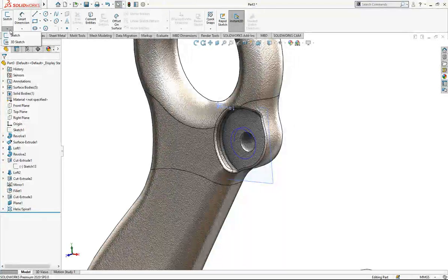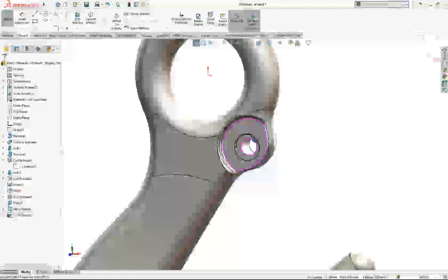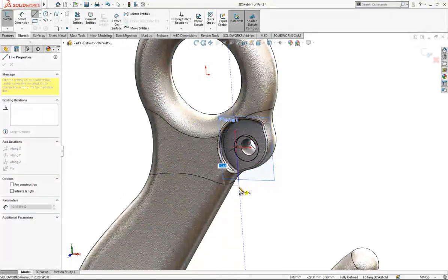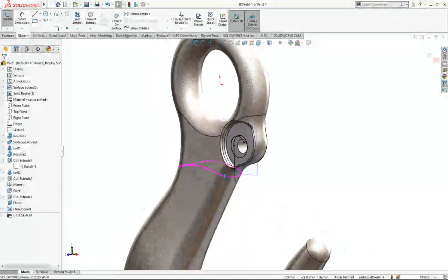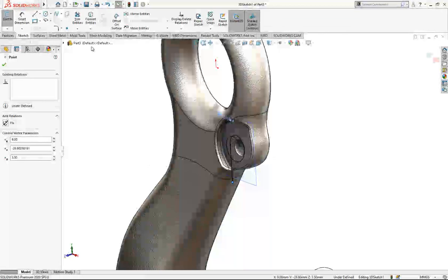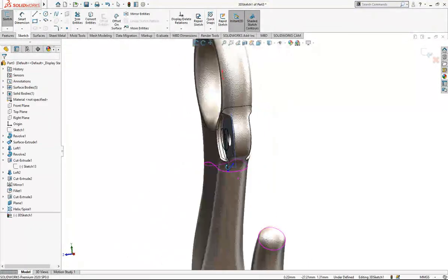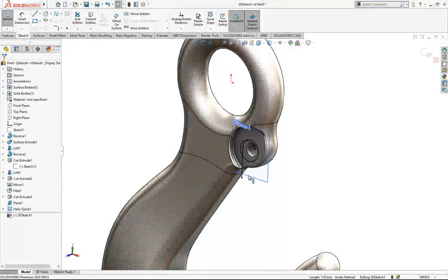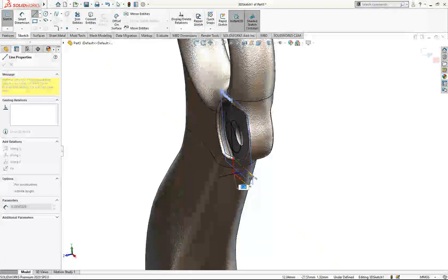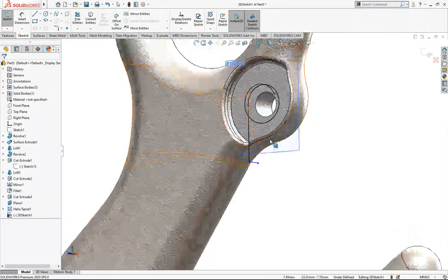After this operation, we go to 3D sketch and we convert this to a normal sketch. And now I pick here a line in the Y direction according to me, and I pick here another line, but it is not in the Y direction, it will be in the Z direction. For that, I should click my tab, and it is done now.